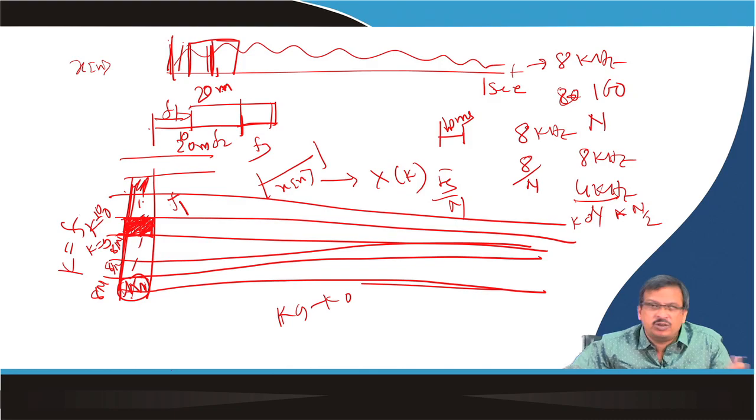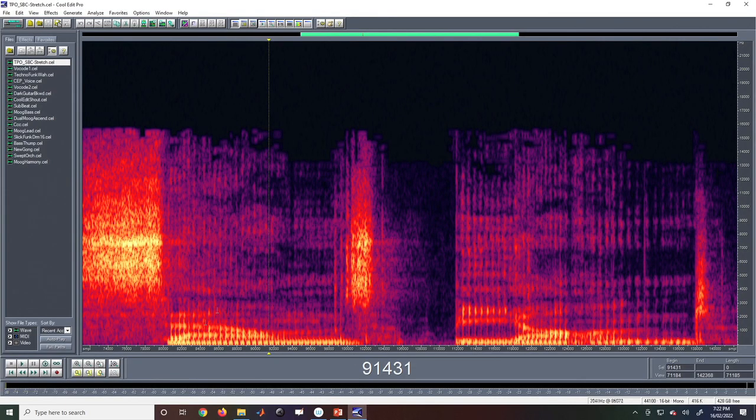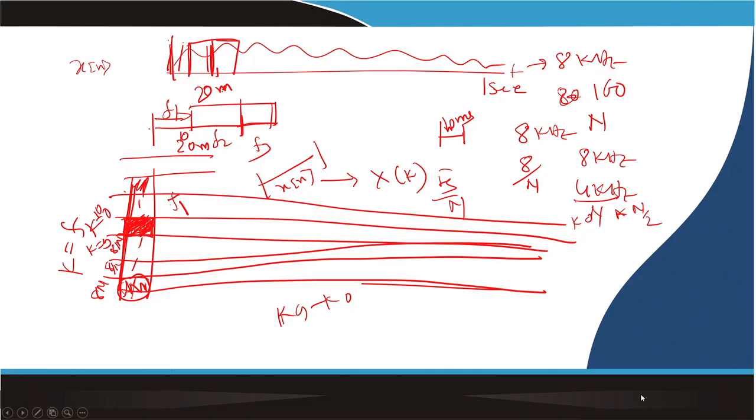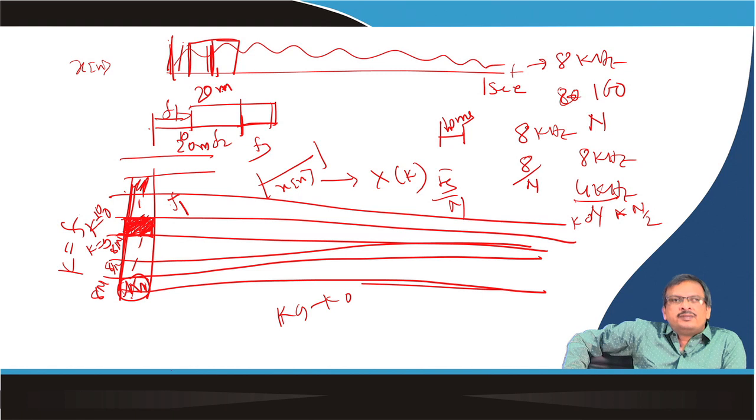So, when you see the spectrogram, you can see there are vertical lines and horizontal lines. Vertical lines correspond to the time resolution, horizontal lines correspond to the frequency resolution. Is it clear? So, that way I can easily draw the spectrogram of any signal. Okay. So, this is the application, and also when we analyze the signal in the frequency domain, spectral estimation, I will cover that part.